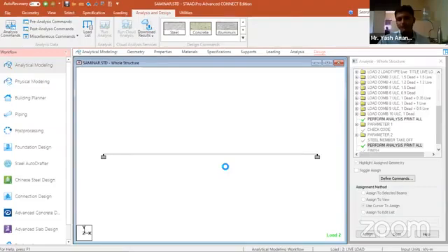Then there is the option View Output File, go to post processing mode, and stay in modeling. What is View Output File? It is the output of the analysis file. Go to post processing mode. As we saw earlier the shear force and bending moment, this time we are going to see the output file.